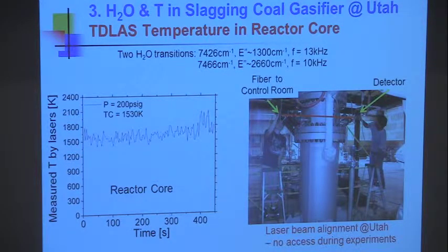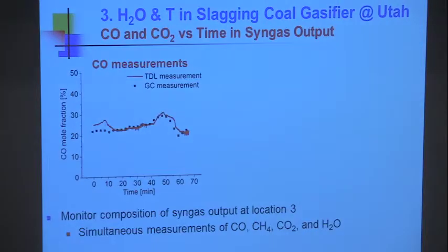And so we finally concluded that most of these fluctuations were actually real. It didn't affect the operation of their system, but it was news to them. How did they ever measure temperature? All they could do was put a thermocouple somewhere embedded in the ceramic liner. That's the closest they could get to temperature. Can't stick anything inside that coal-fired reactor. So we sent light. That's the thing you could transmit. Even though we only had a small amount of light, it was enough.